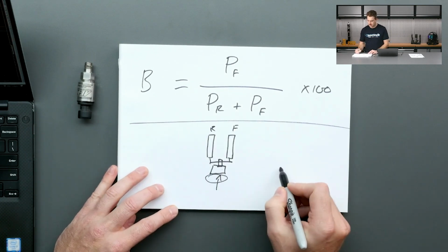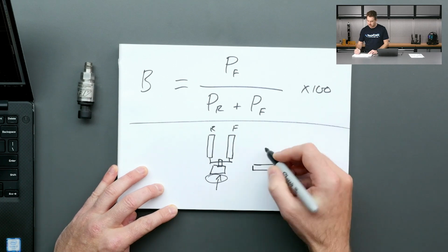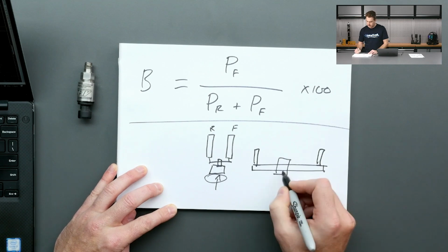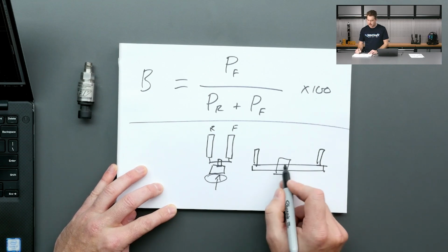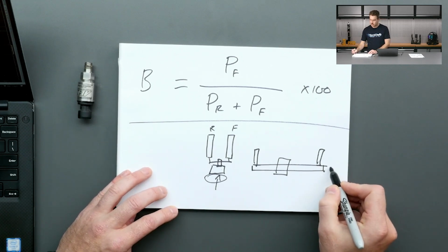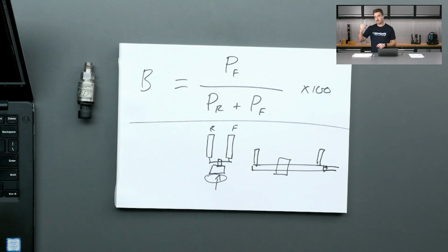Zooming in on that a little bit, if that's your bias bar and this is the connection to the master cylinders, this trunnion is normally on a type of thread, and there's usually a mechanism to connect to the bias bar, which is what that knob is connected to, essentially rolling that trunnion bar.